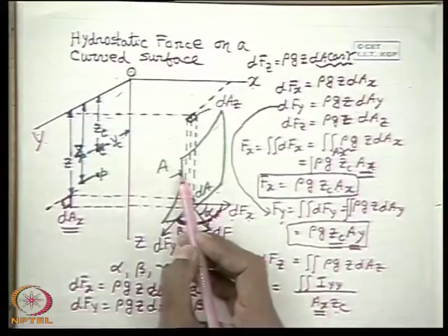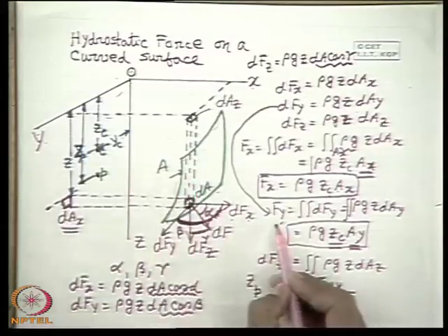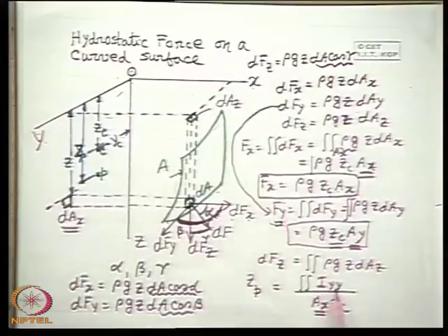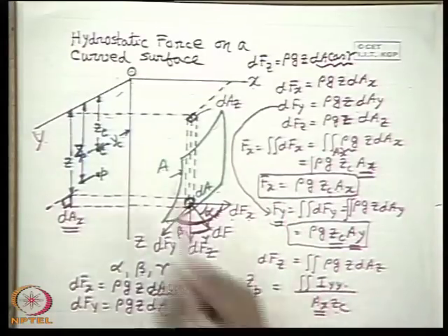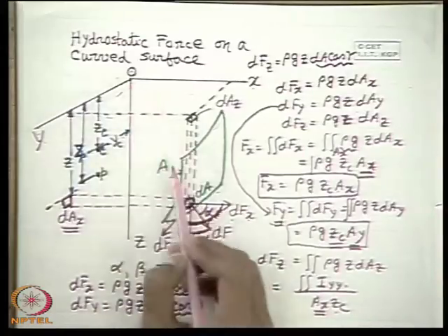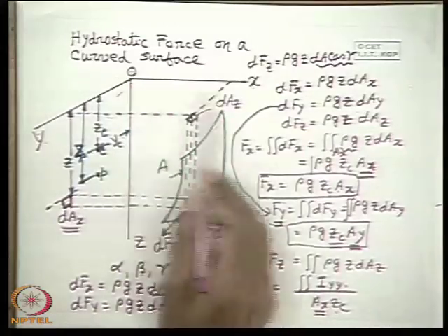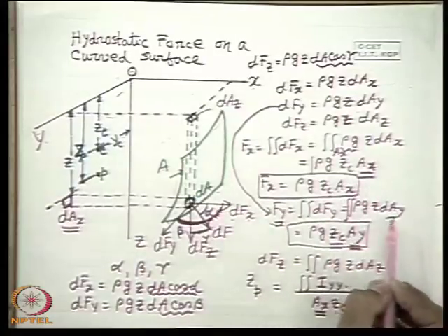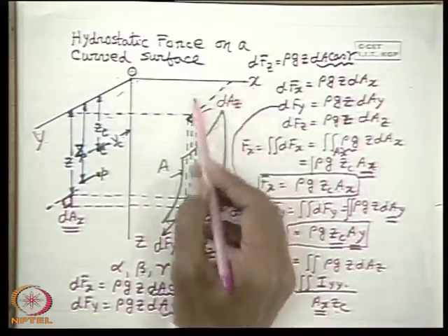In a similar way we can find the pressure center, that is the point of application of Fy, by applying the same equation, that is the second moment of area of the projected area on the xz plane, Ay, about the x axis divided by this.